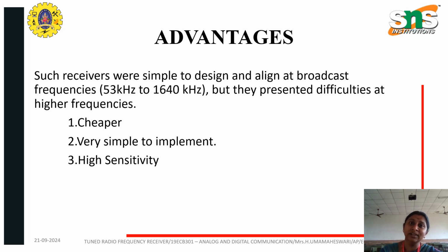and then it is given to the three different amplifiers, where three different frequencies are also used in the three radio frequency amplifiers, which are tuned. That three RF amplifier frequencies are tuned all together at the same time. The three frequencies being tuned together is called ganged tuning. Then it is given to the detector and finally to the speaker.